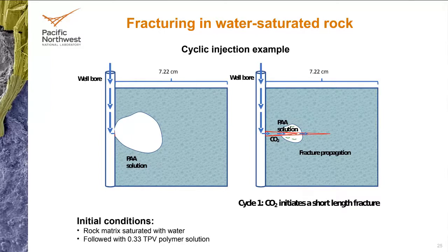And what we see, and unfortunately, I'm sorry, I forgot to put a slide, is basically the pressures: the flow rate is constant, but the pressure increases, and then boom, it falls down. That is when the fracture has gone all the way to the surface of the rock, and then it meets atmospheric pressure. So what we see is just the pump pressure going down, and then a lot of fluid coming out of the rock. At that point, we stop the experiment.